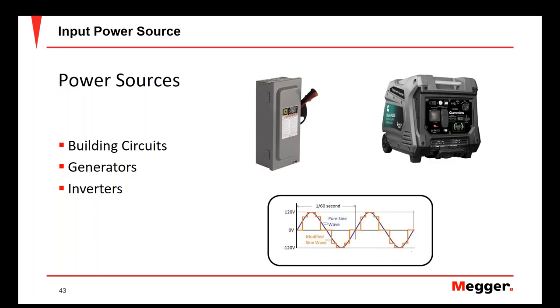I had an experience one time where I was testing in the field, and the customer was providing test voltage for my test set. They didn't adequately size not only the panel, but the breaker that was feeding the test set. Not only did the feeder breaker that was providing voltage to my test set trip, the main breaker in the panel tripped, and it took down their entire process. So that's why considering the needs of the test set and what you're doing whenever you do this type of testing is very important to understand.